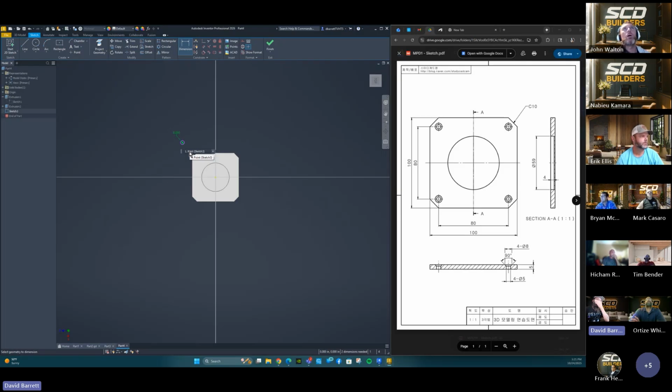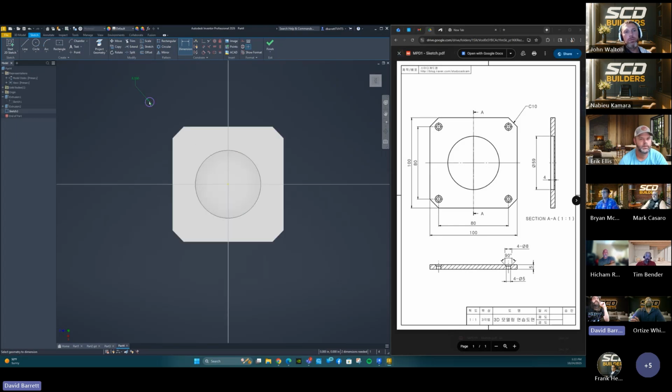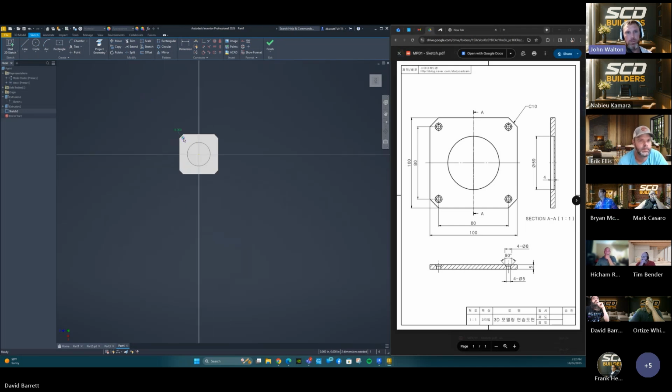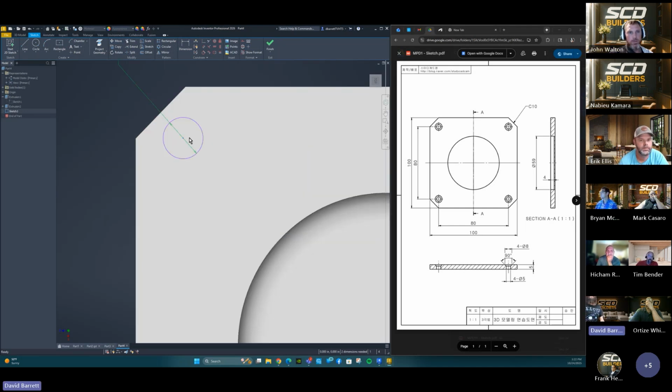When I moved my holes, I had a reference line show up, and it centered it with those two points. So you just took your hole and moved it. I did it while I was creating the sketch, I don't know if that matters. I see what you're saying, the little purple dotted lines show up and line up the corner. I'm seeing that too just now. So it brings it to both corners.